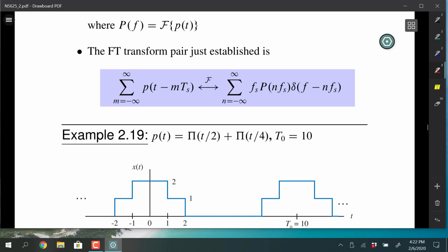If you're wondering where all this is going, well, you need this background in order to understand modulation theory and communications. It's just kind of common sense stuff. And pulse trains, other things, they formulate the basic radar signals that have been around forever. Send a burst of energy, shut it off. That's where the pulse train comes in, and listen for the reflection coming back from all of the terrain. So does that make you understand the pulse train, why it's so important? It's fundamental. You get interrogated by a pulse train of RF, and then your signature is how you reflect the RF back to the receiver.